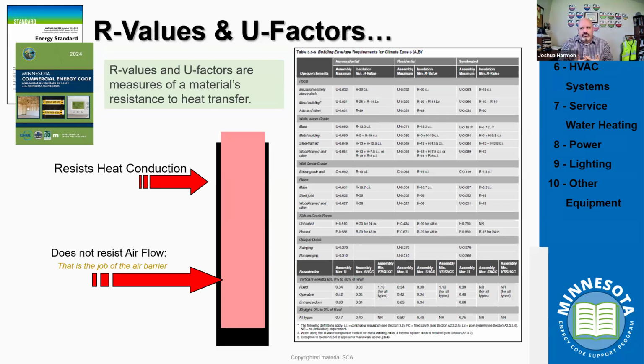And that pressure differential is going to cause that air to transfer through. Insulation, for the most part, is designed to slow that, to impede it, not to stop it completely. And so it's that transfer of thermally charged air through that system that causes a lot of times that air to be deposited in the actual insulation, and then it resists the further transmittance of heat through it.